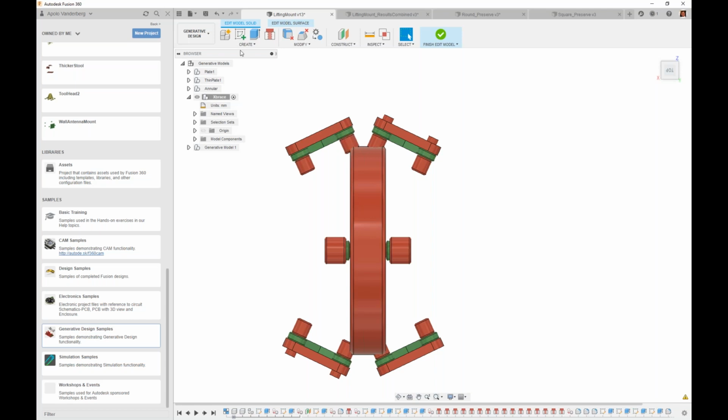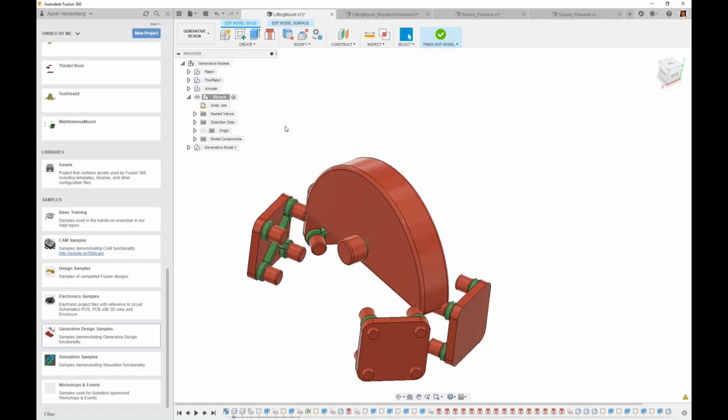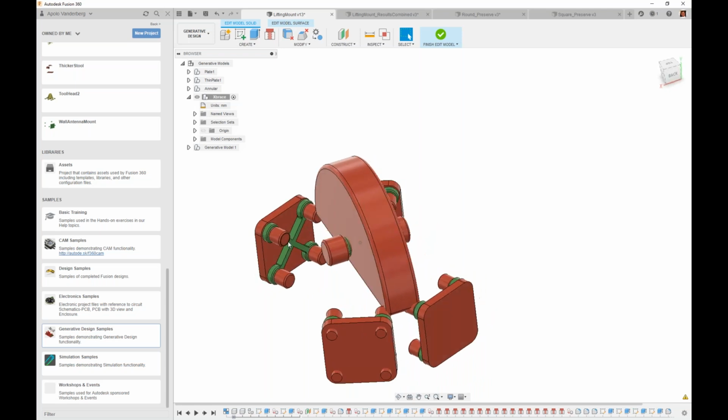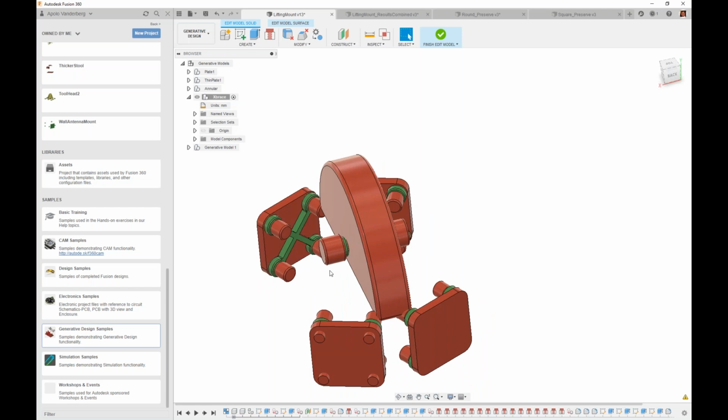Additionally, we didn't talk too much about it within this edit model space, but sometimes there's benefit to CADing a starting shape, right? So instead of letting the software dictate the initial shape and then whittle away from there, you can seed that starting shape, and then we will grow or shrink as needed from there. Sometimes you could build that starting shape to be your minimal features, and have it grow to what's needed to maintain the load cases you have assigned.